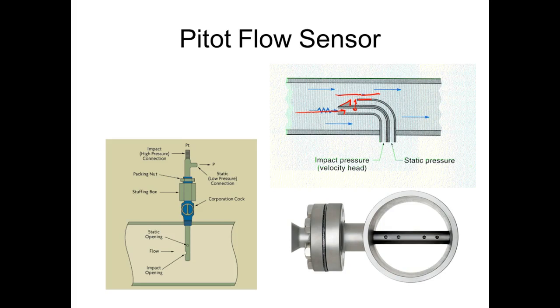So what was happening on those sensors was it was telling the plane that it was going to go into a stall, so it dipped the nose down to pick up airspeed. Well, the problem is it was coming in for a landing, right? And they dipped the nose down to compensate for airspeed, and the pilots didn't have time to figure out what was happening. And what happened? Yeah, it crashed. Same reason. The angle of attack sensor was bad, saying the plane was fixing to go into a stall.